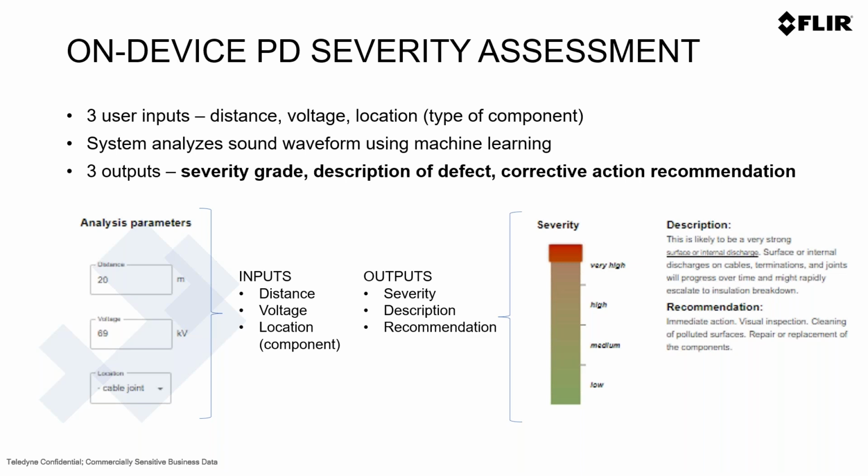There is not any kind of secret there. We identify the partial discharge by understanding the wave of the PRPD pattern. But if you want to get the severity level, description, and recommendations, you need to introduce this data to get it sharp and correct.